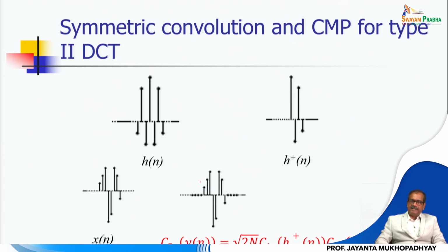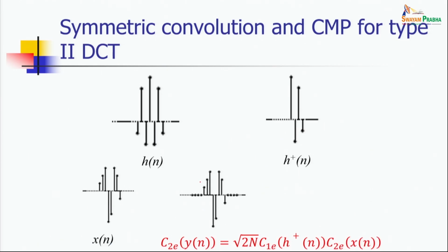Since it is symmetric, half of the response is sufficient. Now, it could be symmetric, it could be antisymmetric also. But the only thing is that half of the response is sufficient for specification. For example, if this is my filter response and this is the 0th point or point of symmetry, only these values are sufficient to specify the whole filter.